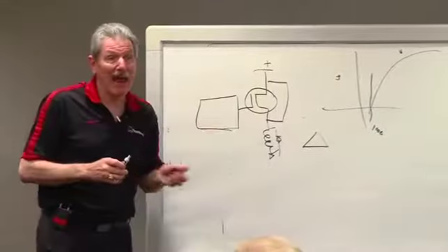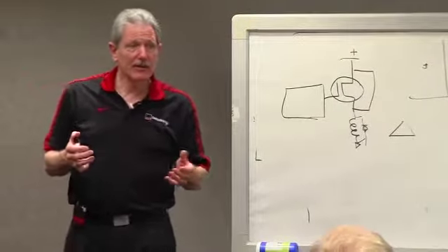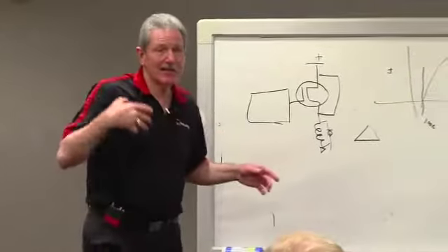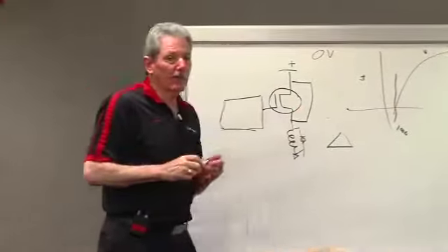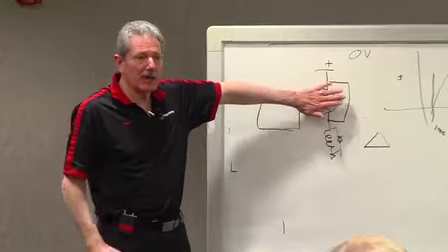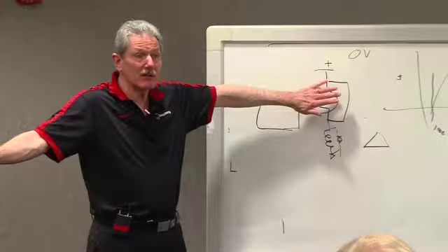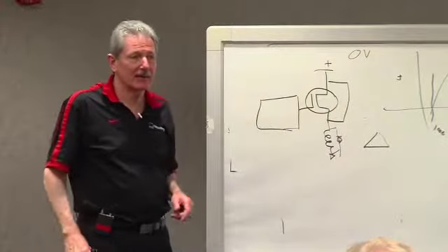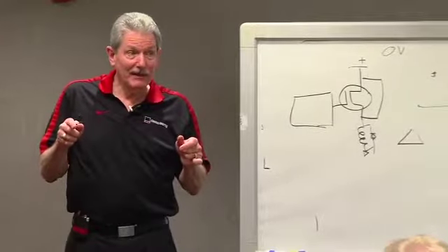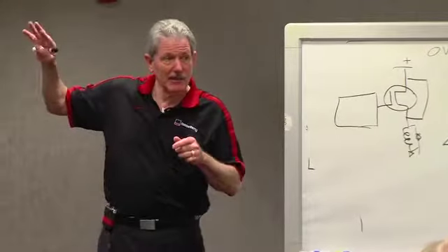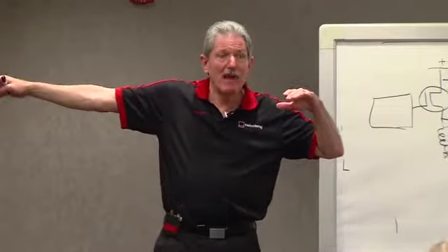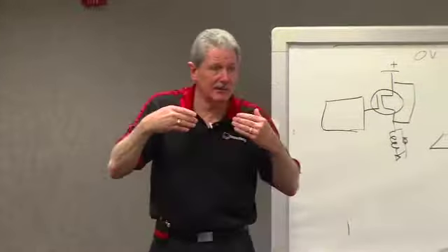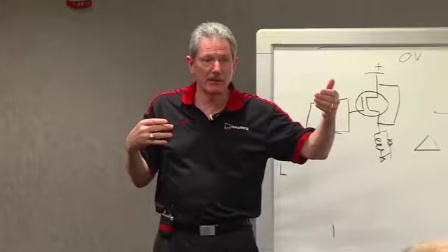This is really bad, because there's nothing you can do inside the regulator except tell that you have a fault. This is overvoltage. Overvoltage means I've shorted the output. I have no control. There's nothing that I can do. I can't disconnect anything. But we want to know about that because all of the electronics is now going to have an elevated voltage. The battery is going to boil, and it's a bad thing. So we tell the driver, you have an overvoltage condition.